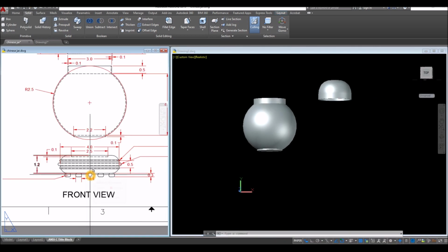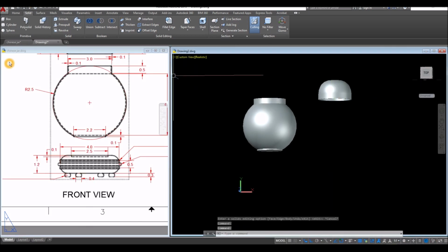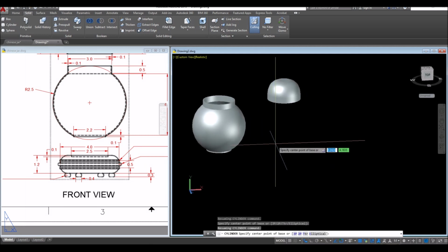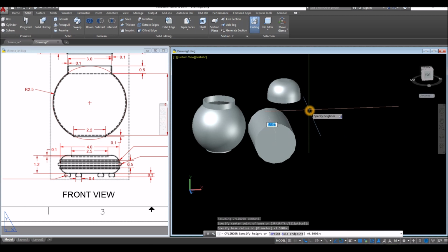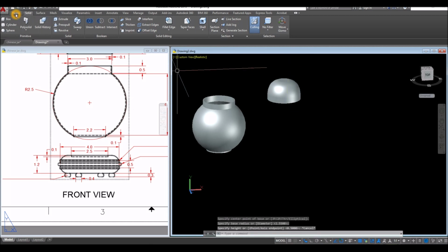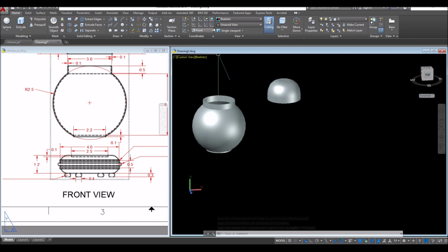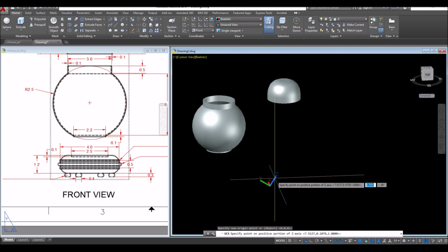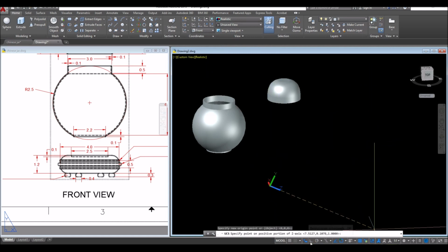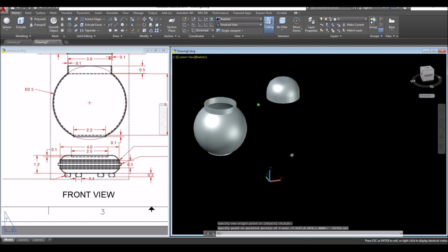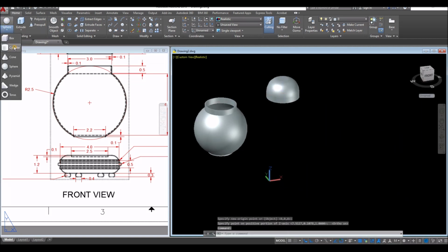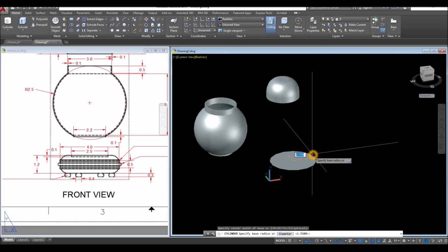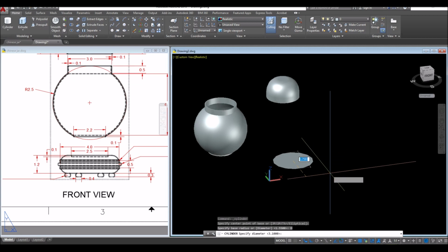Alright, I'm gonna use cylinder. So go to home, or you can still stay inside the solid and select cylinder inside the primitive panel and click anywhere on the screen, and as you can see the direction is not what we wanted it to be. So go to home and inside the coordinates panel, click this Z-axis vector and point your Z-axis upward and turn this on again, upward, and select cylinder, click anywhere here and enter, just right click, select diameter option and enter